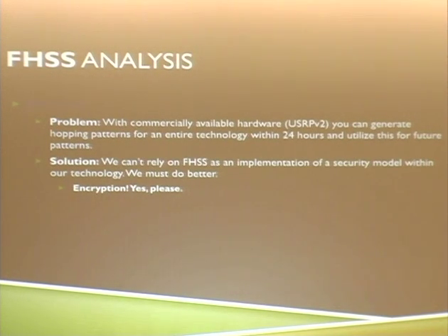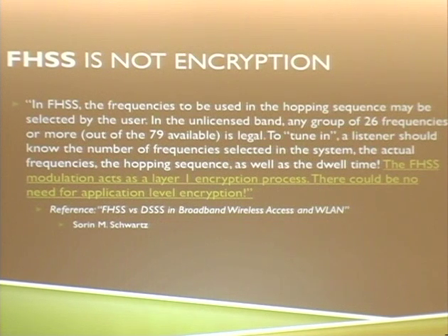What's the vulnerability or the attack vector? Basically, as we saw, if you were here last year, Osman did an all-channel Bluetooth monitor device setup using USRPs and basically generated entire hopping patterns within 24 hours and searched the hopping patterns for the solution. So we can't really rely on frequency hopping as a primary implementation or security model. We obviously have to do a bit better than that, and include encryption in what we're doing.